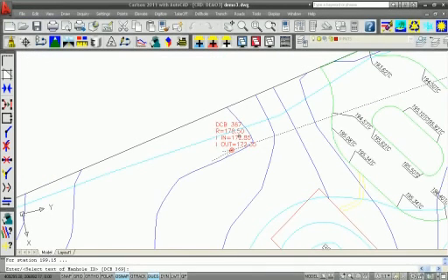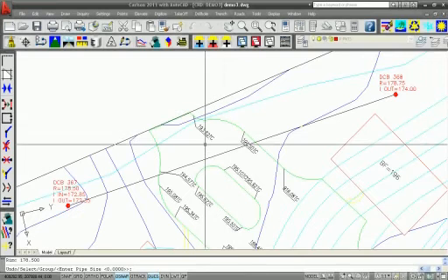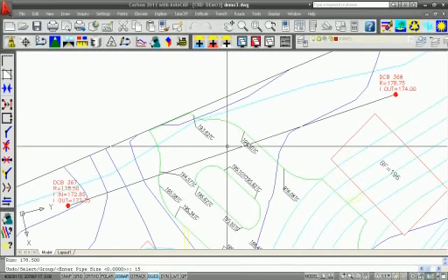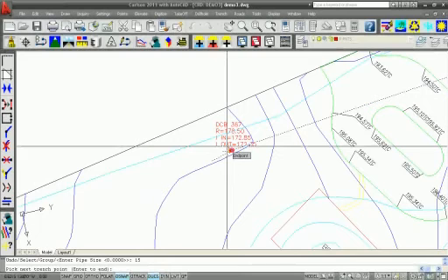Okay? Select text for the manhole ID. Select that value. You can see right above here it's reading that value off of the text in the drawing. This is something that would also work with that new PDF. If we converted all this text from a PDF, this command would now be able to work with it. Invert in, the invert out, and the rim elevation. Okay. Pipe size between the two, I'm going to say 15, and pick the next point.